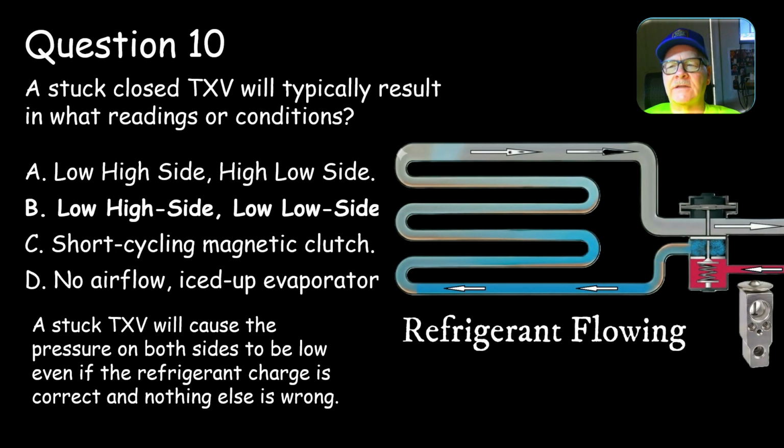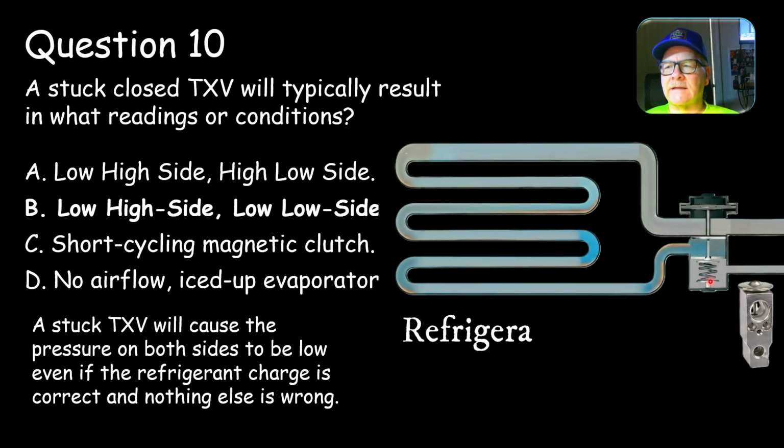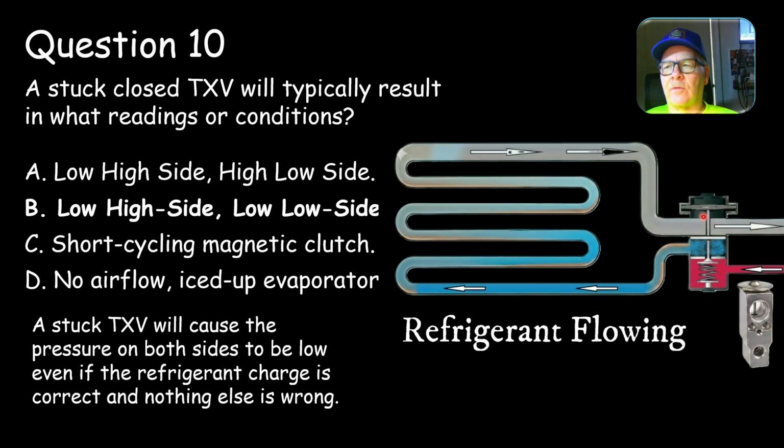Alright, this one here, watch this video I created right here. This is basically showing you, if you'll watch this little thing over here, when it closes up, no refrigerant can go through the evaporator. That keeps the evaporator from icing up. When this line is cold, that diaphragm is going to pull that thing closed. It doesn't have much of an orifice there.